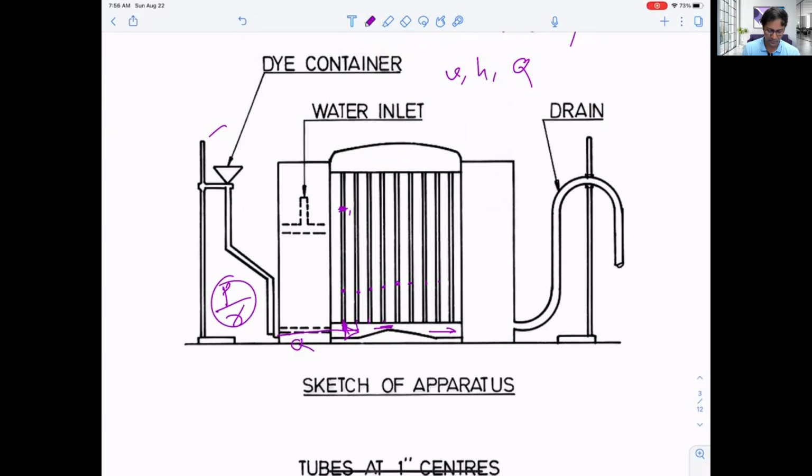If you want to measure pressure right here, you have to see the height of the water inside that tube, capillary tube or piezometer. Then we can measure that, okay, it is the pressure head at this location. So what is actually happening? Why are we changing the diameter here? Only to test if the Bernoulli's principle is valid or not.